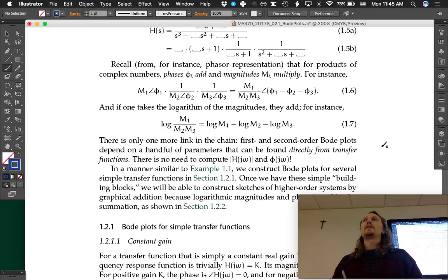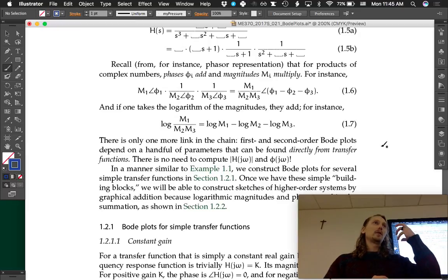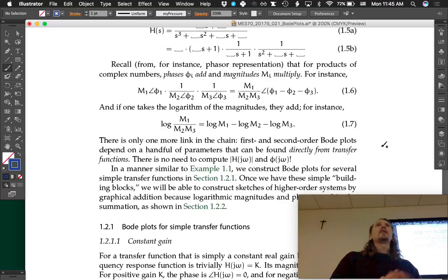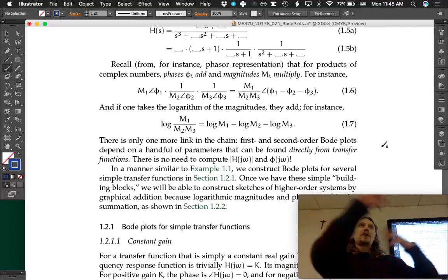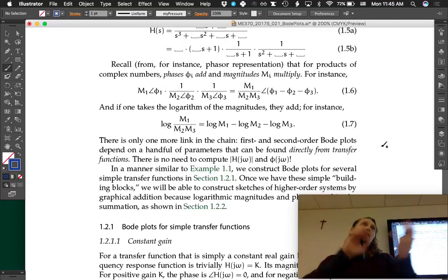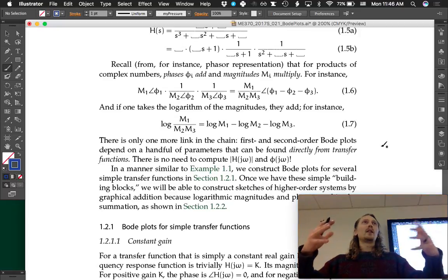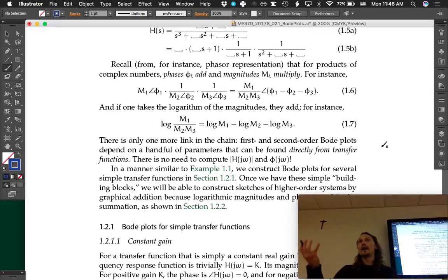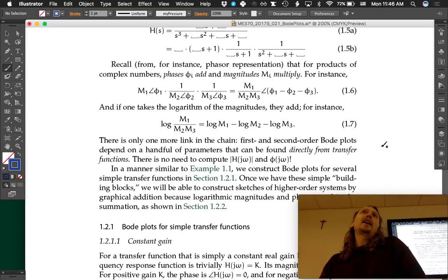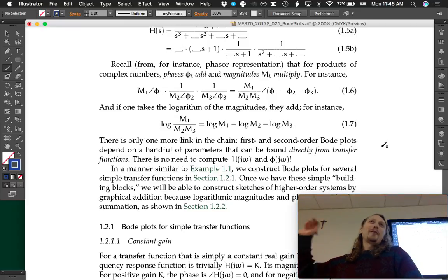People used to do this because they wanted to know what the Bode plot looked like at first, and then they wanted to change it. But now we do it as a design tool, to have an intuition for how, if we were to change the time constant by this much, that would change the Bode plot. We do that so that we have a feel for it. It kind of feels like we're learning an archaic thing, like how to sketch things, but it's actually a way of honing our intuition for designing these systems. That's really the value in it now. Otherwise, I'm a huge fan of throwing away archaic things. I really like doing that, but there's value in some of them, and we have to pay attention to that.